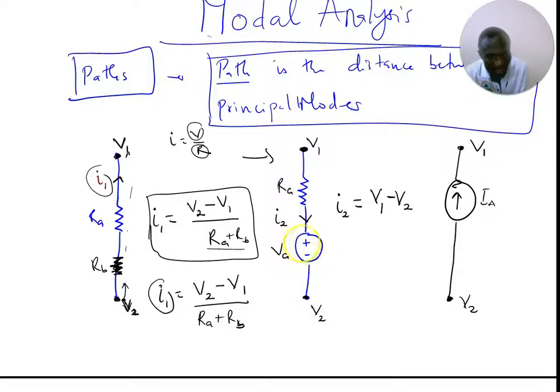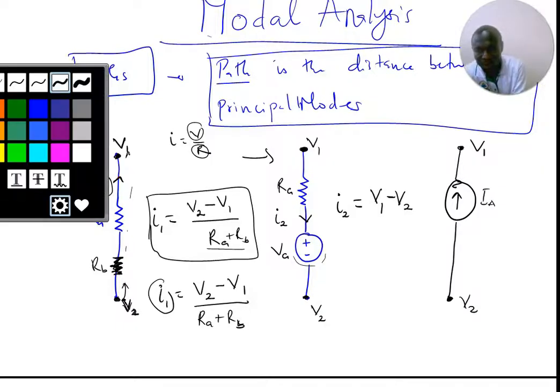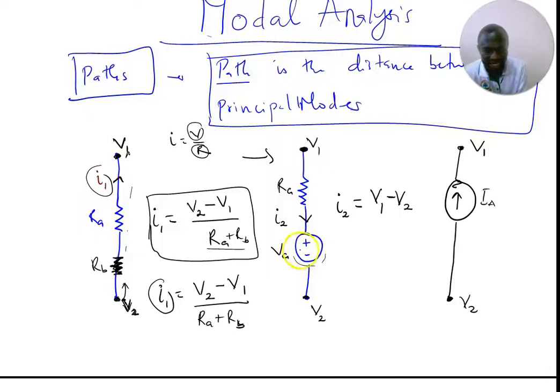At this time, there's a voltage source here. And we need to add the voltage source to what? The voltages at the terminal. And how do you do that? We just imagine, or we just look for the conventional flow of this voltage. See, what's the conventional flow? The conventional flow is moving what? Upward. Right? Yes. So since the conventional flow is moving upward, we ask ourselves, if this voltage is to generate what? Current. Will it oppose the I2 or will it be in direction with the I2?